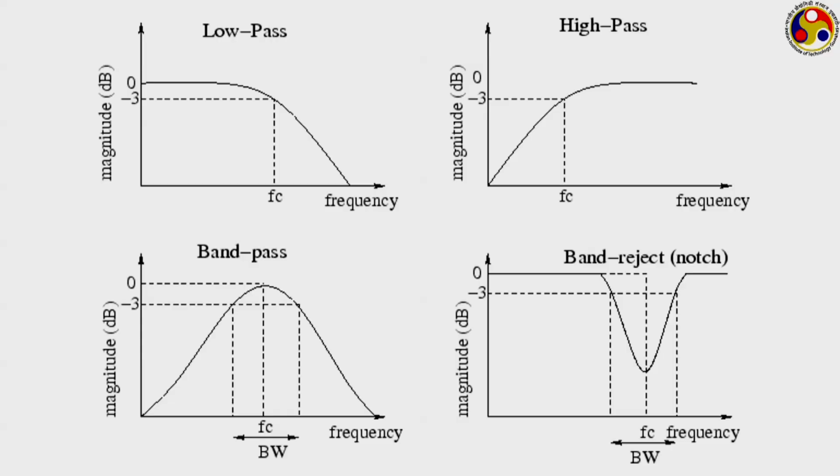Just one example about how sometimes we can use the frequency response to our advantage, that is what is done in filters. Here on this side we have the gain and on the horizontal axis the frequency. Now, over this particular range the system is showing a constant gain, and after this there is a drastic drop. We can use this sometimes as a filter, that is, when the amplitude drops below this particular value, the signal will not be allowed to pass through.